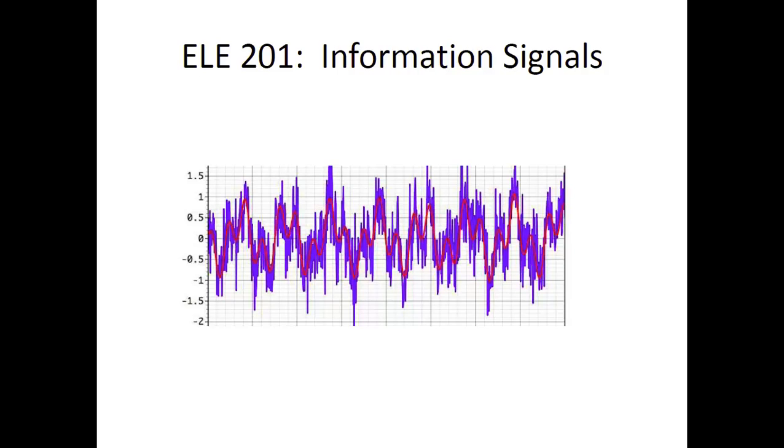from what we're talking about in this course, what we'll learn about. Because it turns out different effects depending on how you do the average. If you just do an average, if you take some window of points around, so what we mean here is, to reproduce the smooth signal at any given arbitrary point, you take a fixed number of points before and after. Let's say 5 points before, 5 points after. And that's your new output for the signal at that point, right? This is a moving average.